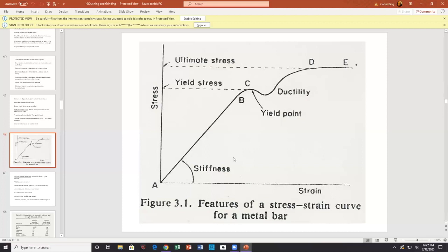Which brings rise that if you have that type of situation, obviously you want to get rid of that energy. Okay, it's there, it's causing a lot of heating. Well, if you put a slipstream of liquid nitrogen in there, that would keep the material from heating up. So the energy goes to crushing and grinding, the energy goes to heating up the material, but you put a slipstream of liquid nitrogen in it, or some CO2 chips, or liquid carbon dioxide, I don't know. Anyway, you can keep the material from heating up during grinding.